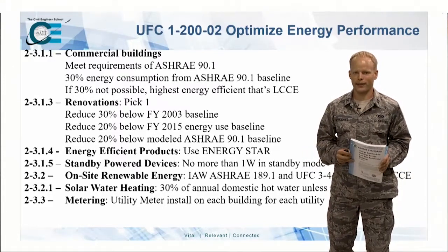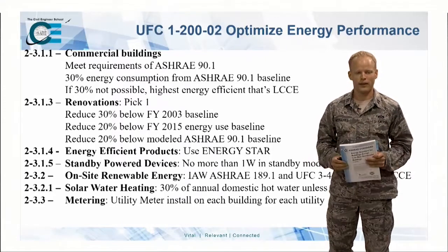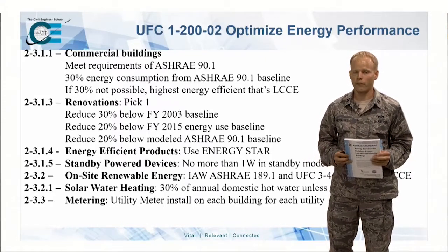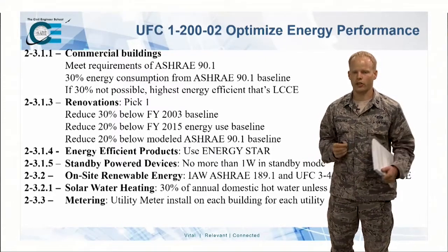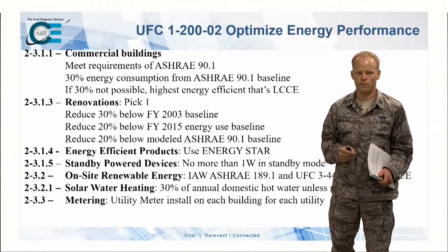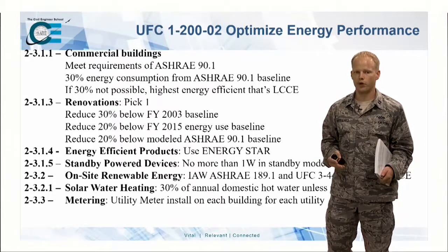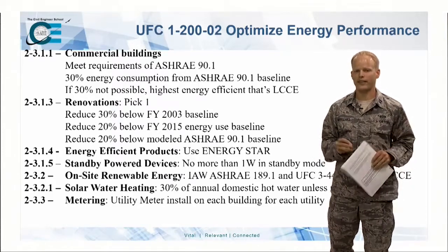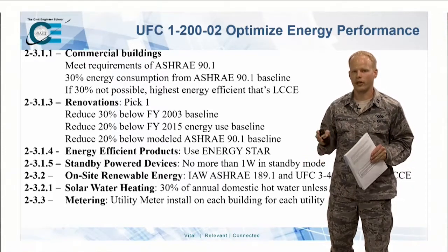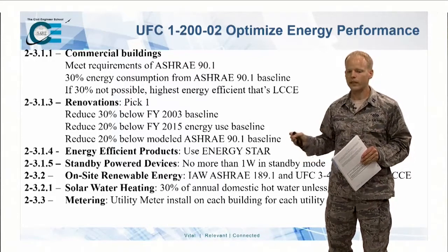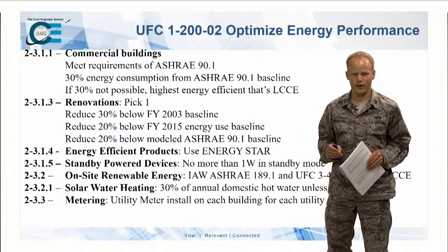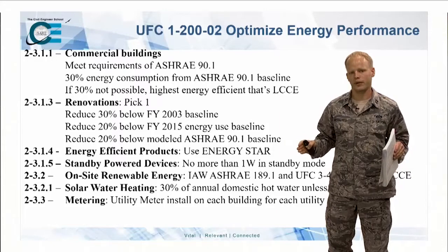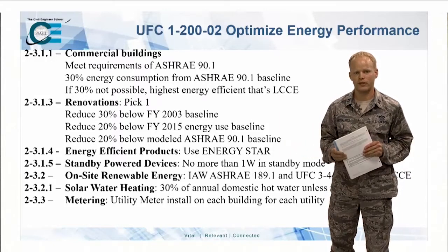So it was a little shocked. I didn't quite read that it was an additional requirement for metering. But for a lot of buildings, it's only if they are going to be your top consumers, they require a meter. But if you want to improve things, you need to know where you're starting. So metering ends up being important. If you've identified a building that you are going to do a renovation on, install that meter on there a year in advance so you can get a full year's worth of data so you can make informed decisions.